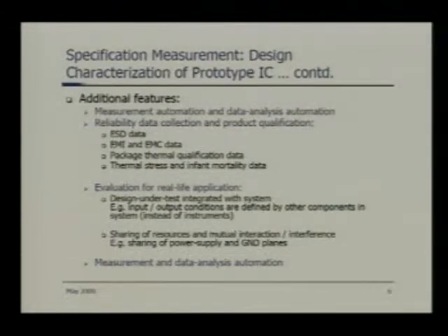Particularly, say minus 40 degrees to 85 degrees centigrade is the specification. You have to make sure that there is no thermal runaway. Thermal runaway means no part within the IC, no junction within the IC, is running so hot that it is going to a melting situation. So basically, you have to qualify for the thermal specification as well.